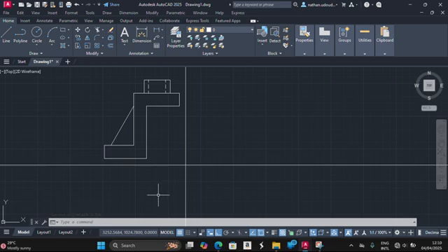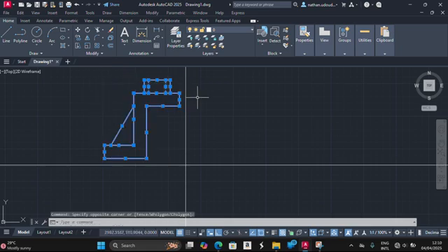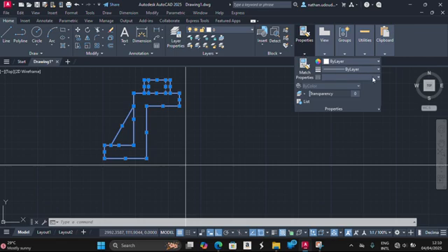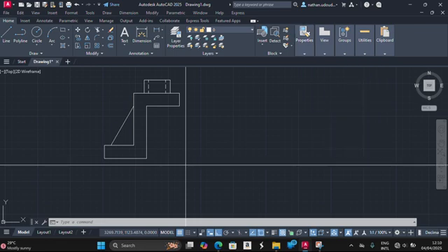So now we can make this one bold. Let's increase the line thickness of the whole of this, so that when we have to dimension, it will not have the same thickness as the dimension. So we come to the properties, we come to line thickness. So let's choose a line thickness of say 0.7. Okay, so it's not thick, so you come here, come to your status bar, this is your line width. Okay, sure, it is asking you to show it or to hide it, so we need to show it, so you can see it's thick. Okay, then you press escape.